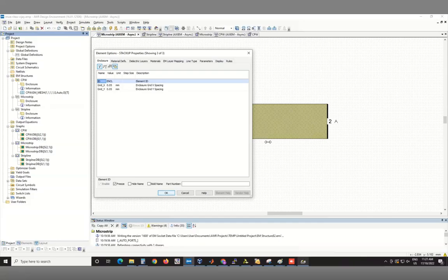But as I mentioned, the grid spacing is only loosely connected with the actual mesh size. It will automatically determine the optimal mesh size. But generally, if you make it very coarse, it's not going to make it finer than that. So that sets the lower limit. You can go very fine, but it may not do it. But you will try some of these things a little bit.